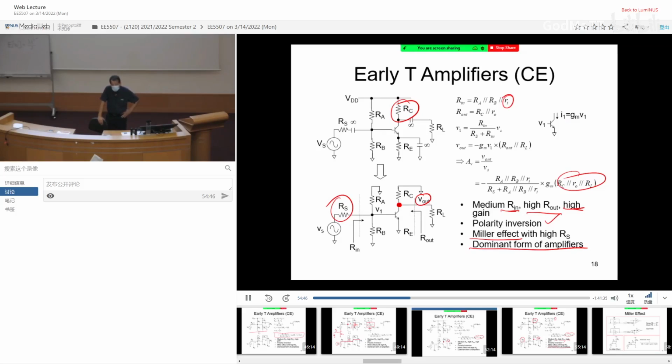Very simple. For an RF amplifier, one of the key requirements is actually impedance matching. We need to match to the antenna, 50 ohm. So the amplifier has to present a 50 ohm resistance. Now you might be thinking, that is easy, right? 50 ohm resistance. But for an RF amplifier, you want to do it without introducing too much noise. And you know, with resistance, it comes with noise. You cannot avoid that. But some people don't care.